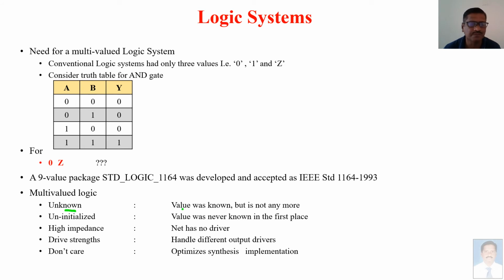First is unknown: the value was known, but it is not anymore. Uninitialized: the value was never known in the first place. High impedance: the net has no driver. Drive strengths: handle different output drivers. Don't care: optimizes synthesis implementation.